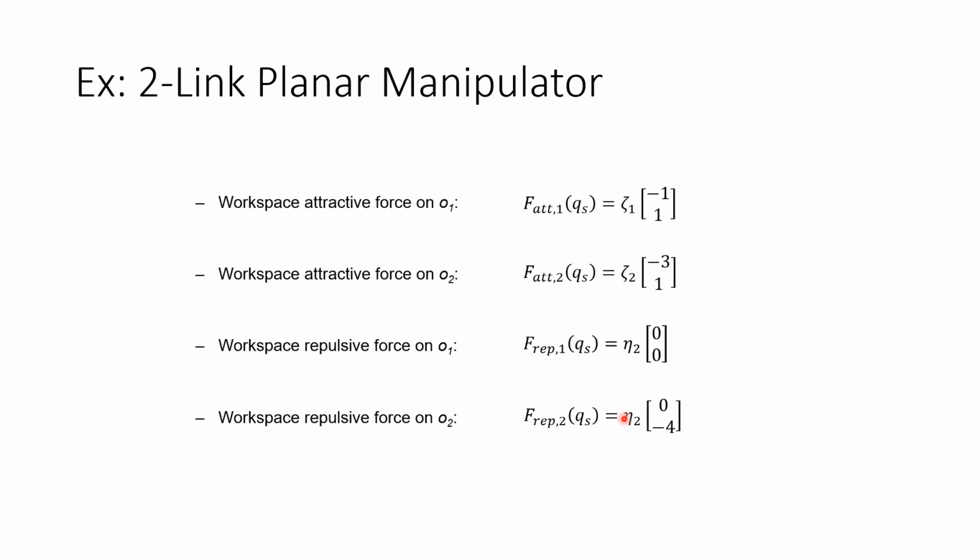So now you have got the realization that the robot, corresponding to especially the Denavit-Hartenberg coordinate frames, is going to experience the attractive and repulsive forces as defined in these vectors, and these are exactly what is going to force the robot to move in a specific fashion. And that is exactly the crux of the potential field method.